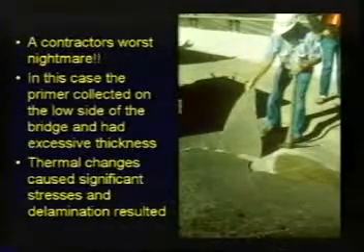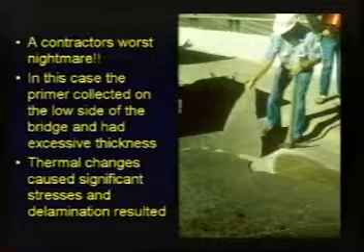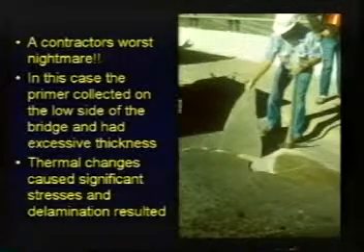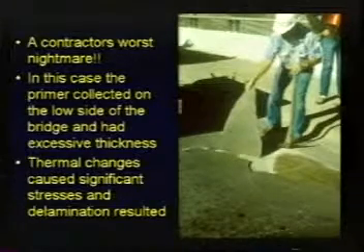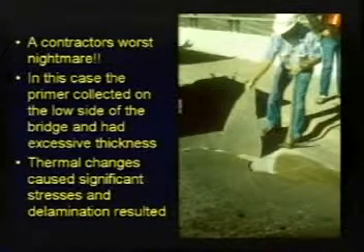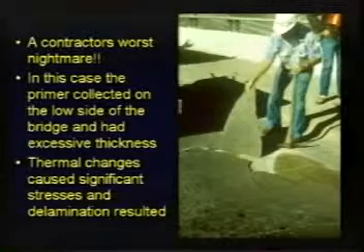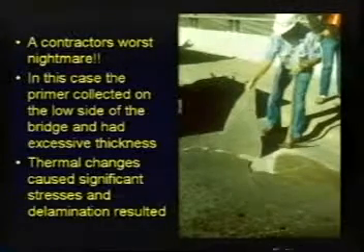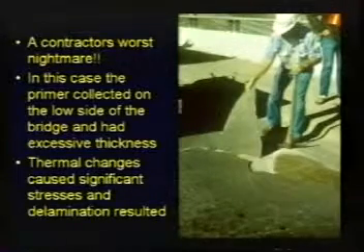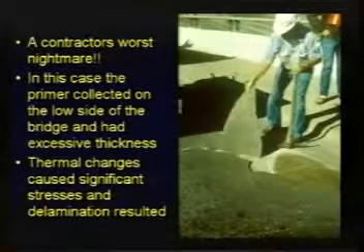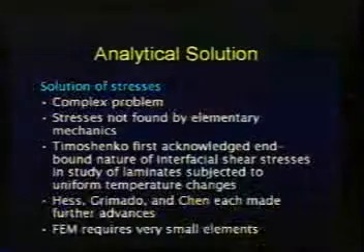And what happens is the contractor's worst nightmare. In this case, a bonding agent or a primer was used, and because it was able to run down the slope of the bridge, it built up to a fairly large thickness, and later on when temperature changes occurred, stresses and then delamination resulted from that effect. And that's something you never want to see on a bridge deck.